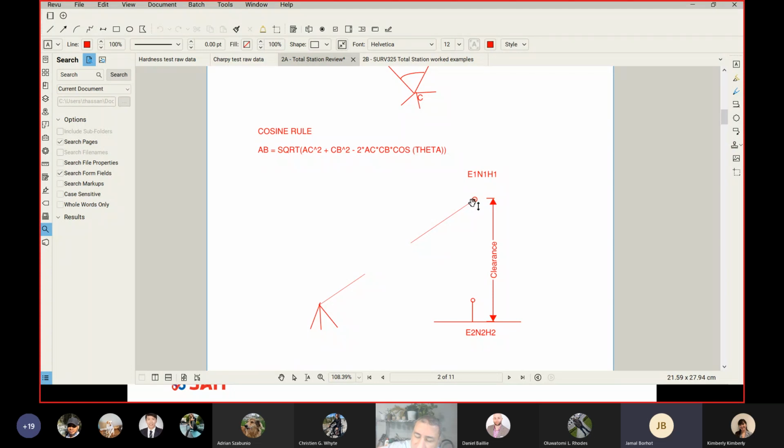100 meters. Thank you so much. That's correct. It's about 100 meters. Now, let me ask you, sometimes you're right. If the distance between the total station and the cable is less than 100 meters, congratulations. No need to do anything. Just use your total station in reflectorless mode and find coordinates.